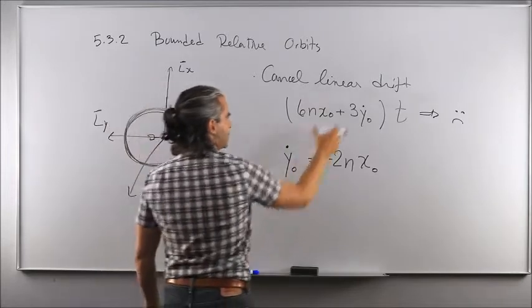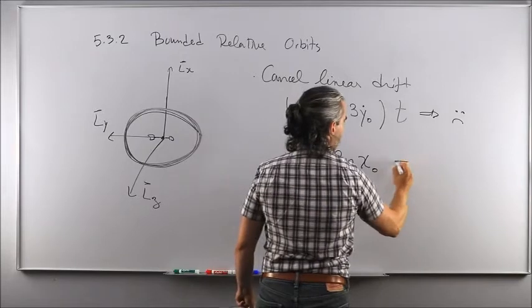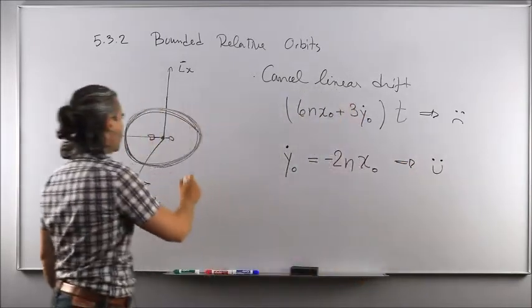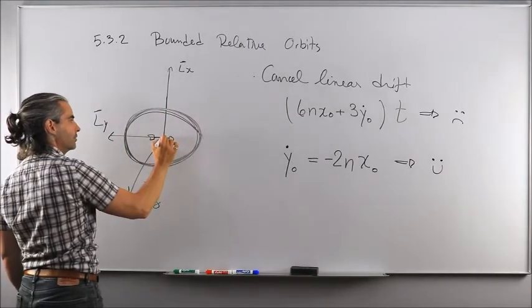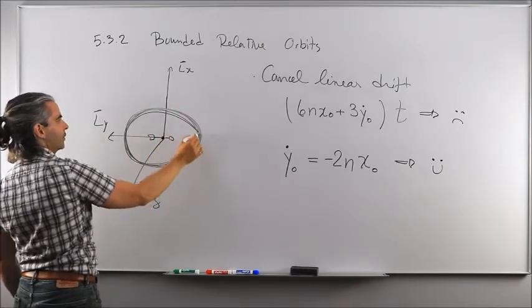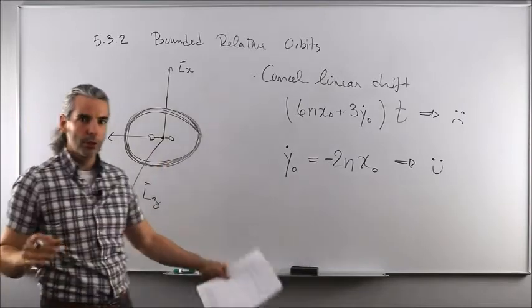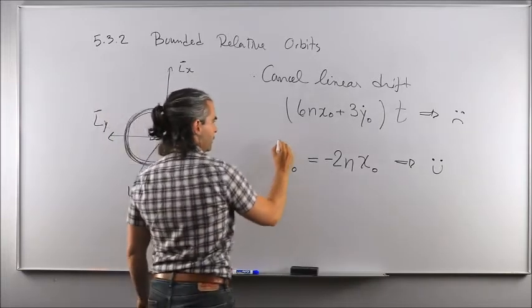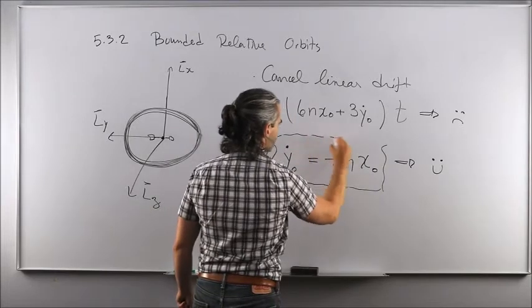And then you substitute this back in here, you clearly see that you get 0 for this term, and that makes you happy because that just created a relative motion, or the motion of the chaser with respect to the target spacecraft in terms of LVLH. That would look something like this, something bounded that doesn't grow with time. And you're able to achieve that solely by selecting the initial conditions properly, okay?